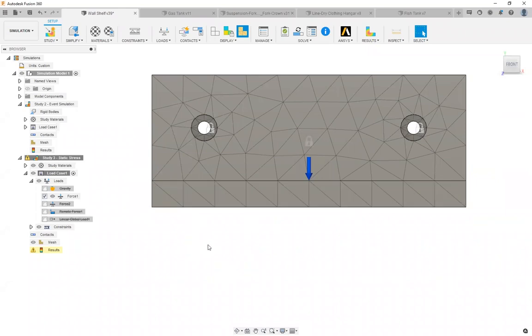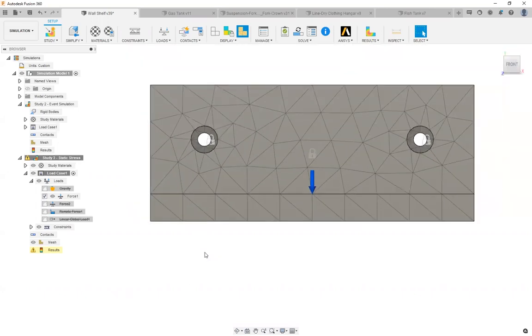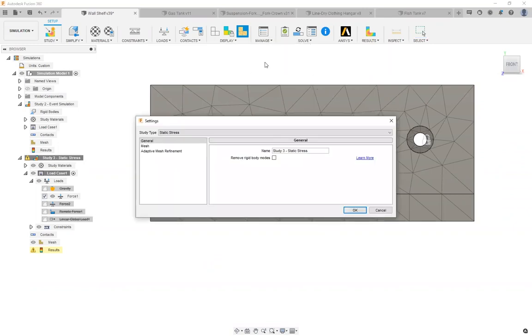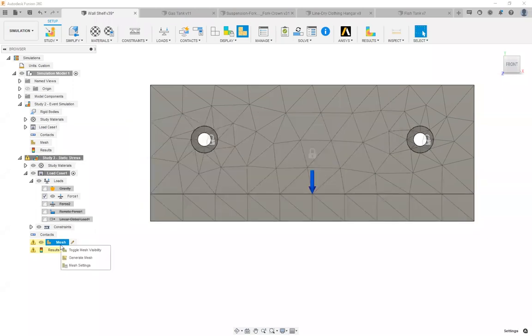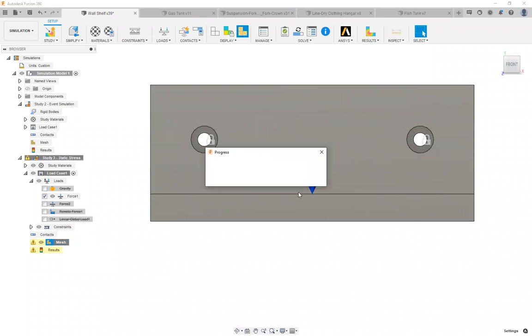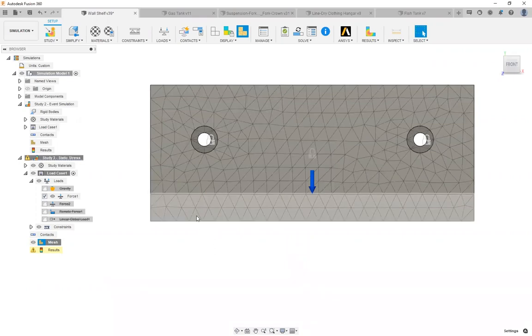So this is after talking to our simulation experts, and they recommended having 2 to 3 different layers if we're bending inside of the simulation workspace here. So one way to go about doing that is if we go up here to our settings, we can go to mesh, and we could lower the model base size to about 4%, 3% there. Right click on our mesh and generate the mesh again. And we'll see if it's going to be 2 to 3 here instead.